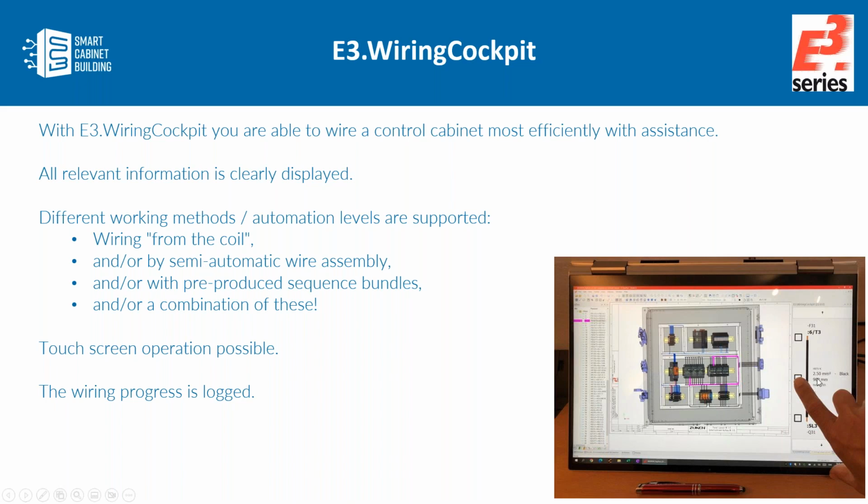Then maybe some parameters are not so important, because the length is cut automatically, but just for information, you see it. As well as if you get such pre-assembled bundles with everything done, all the labeling is done and the wire end processing is done, then you just need the information from where to where, if you get such a bundle